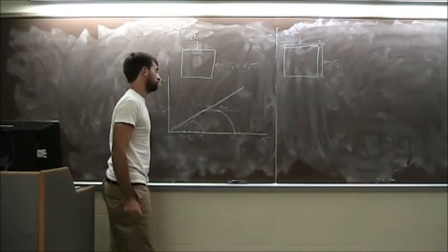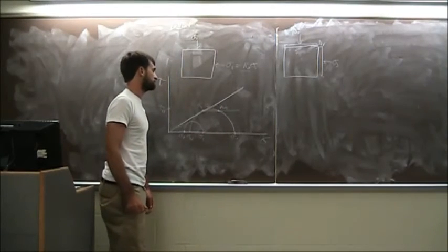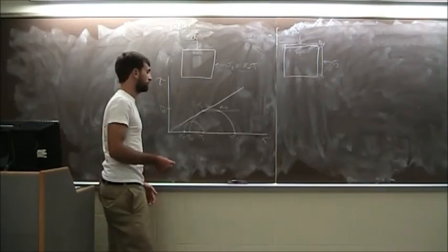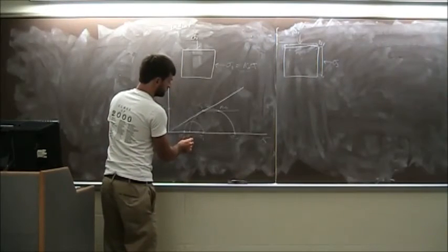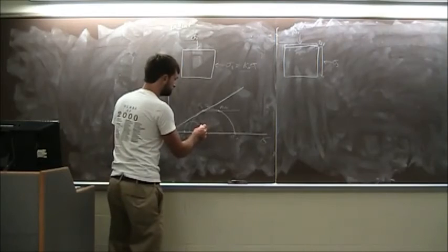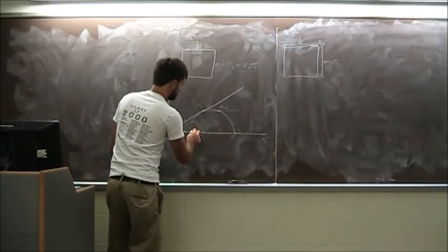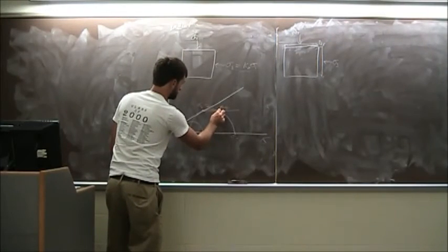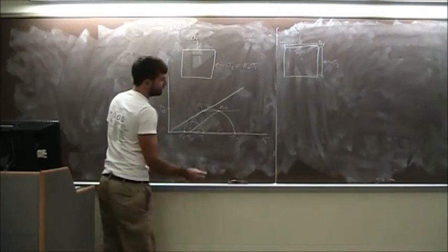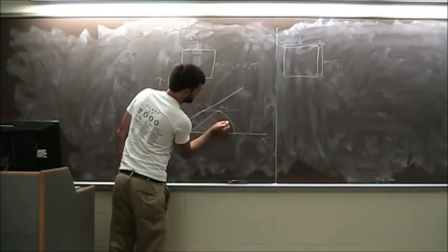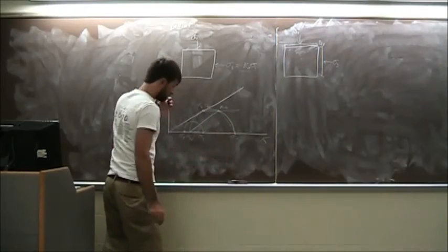And since this pole is the intersection of all planes and the stresses that act on them, we can show where sigma 3 and sigma 1 act now. So sigma 3, if you draw a line from the pole to sigma 3, that's the plane that sigma 3 acts on. And this is the plane that sigma 1 acts on.